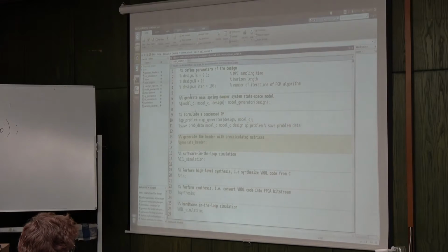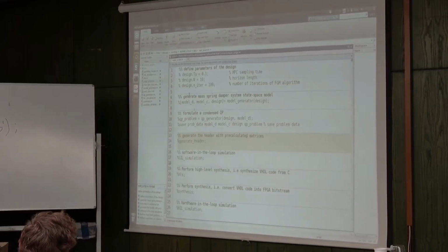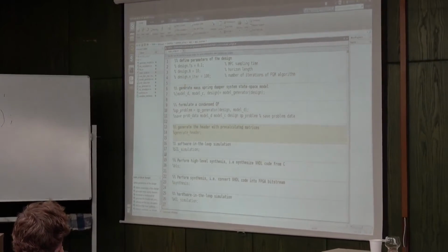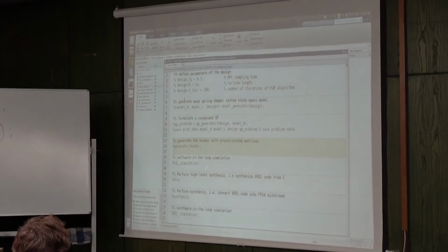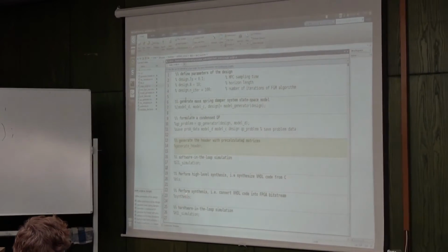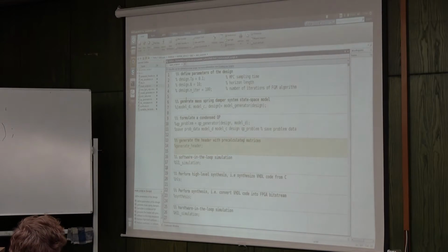I don't recommend uncommenting the whole script and executing all the lines together, because this makes it really difficult to debug. So I would suggest you go step by step. Up to the synthesis stage, you will not need the Z-board. Up to here, including synthesis, you don't need anything apart from your laptop. And for the last step, you will need to connect the Ethernet cable and power on the Z-board in order to see how it works.